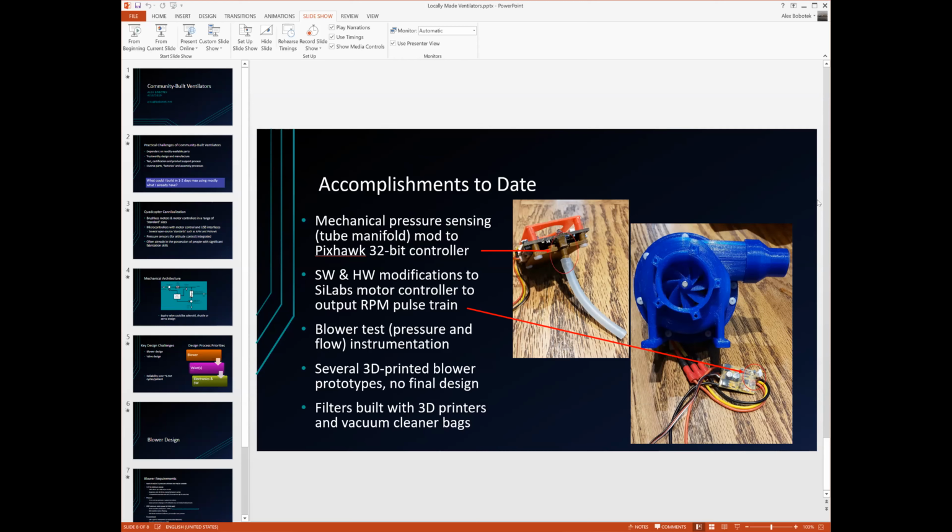I can, I'd be happy to do that. I don't have a suitable turbine design now. I'm working on one. The one that you saw does not meet the requirements. It doesn't build up pressure. I believe there's too much of a gap between the turbine and the housing to generate the necessary pressures. So if and when I get to a point where I think I have something that provides a good baseline for others, I would be happy to post that.